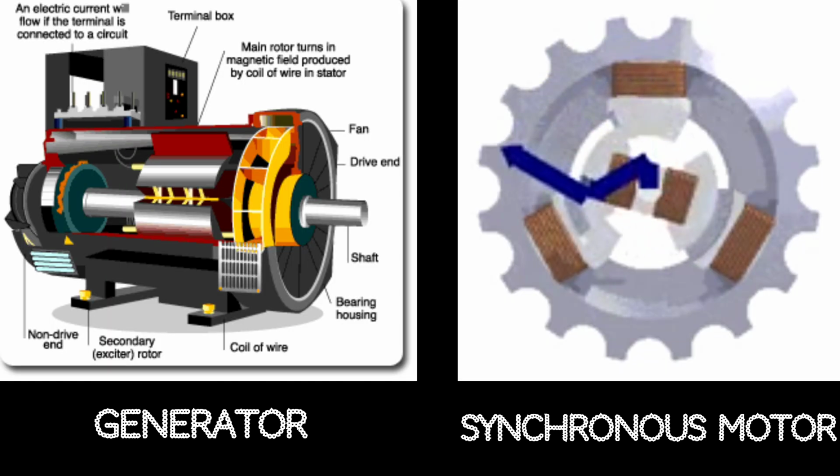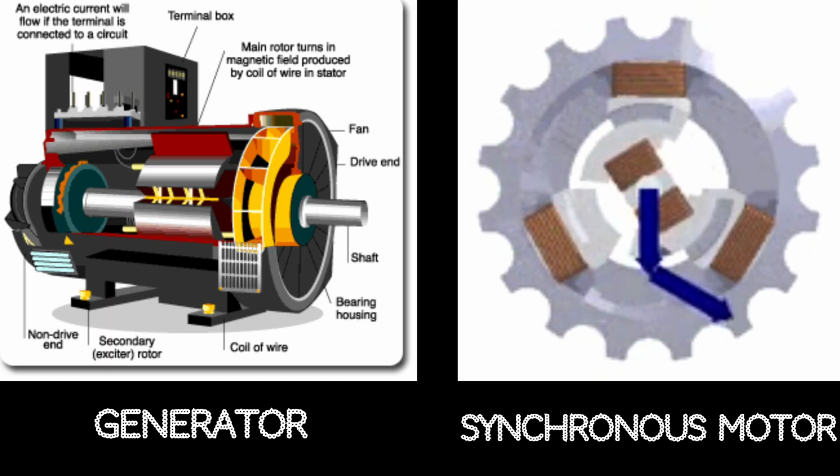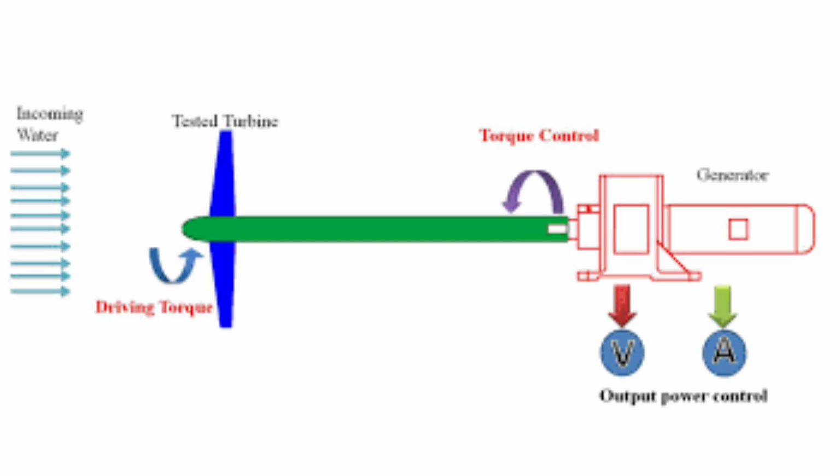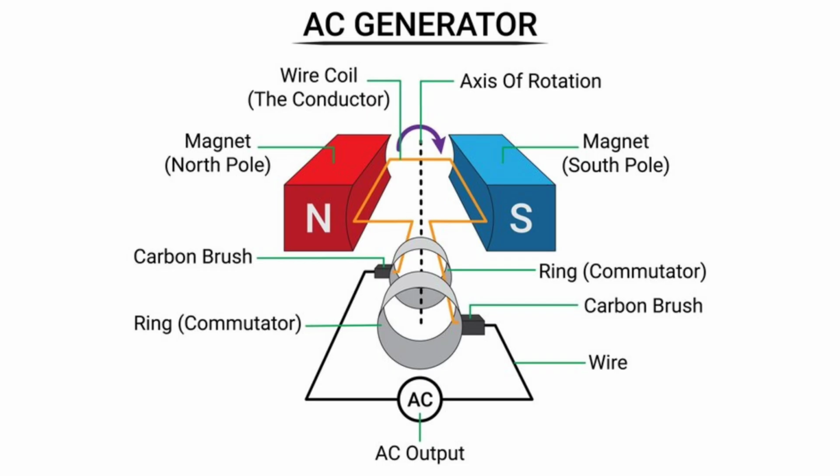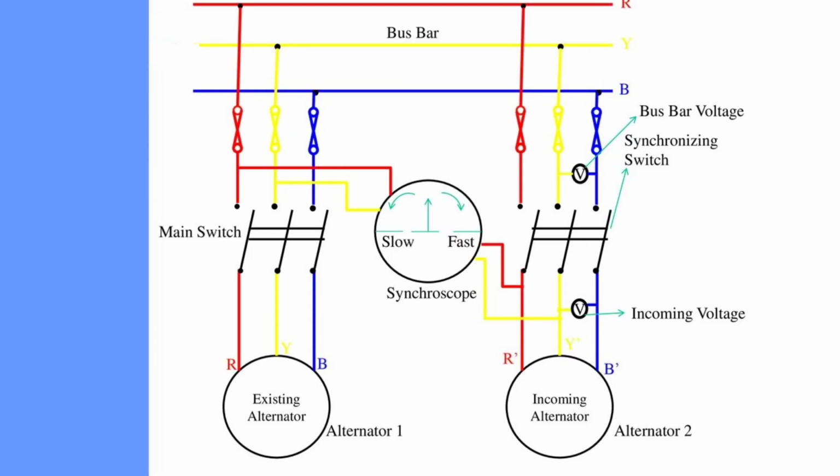A generator can work as a synchronous compensator if the driving torque is less than the total loss in the system, taking necessary power from the network. For instance, reducing the steam flow in steam turbines can result in overheating since the cooling effect of the turbine blade is reduced. By supplying enough torque to keep the rotor spinning at the same frequency as the connecting bus, the generator will draw power from the bus bar rather than supplying power, causing a reverse power flow.